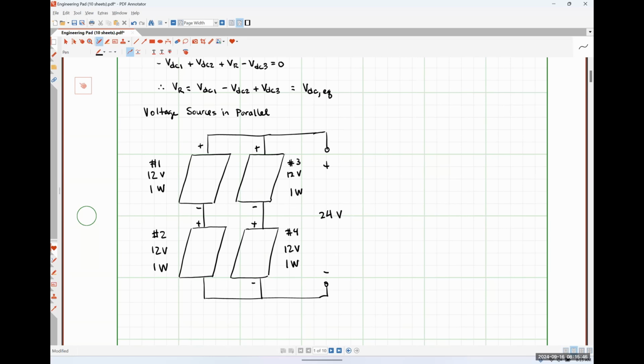Well, adding the second string of panels is going to boost the overall current and the overall power that the solar panel array can deliver. So you'll usually see some combination of series and parallel connected solar panels in any individual solar array, with the goal to provide the correct voltage for whatever application you're looking at, and then you put your strings in parallel to boost the current. So outside of Louisiana Tech, I do some work for a company called Sabre Industries over